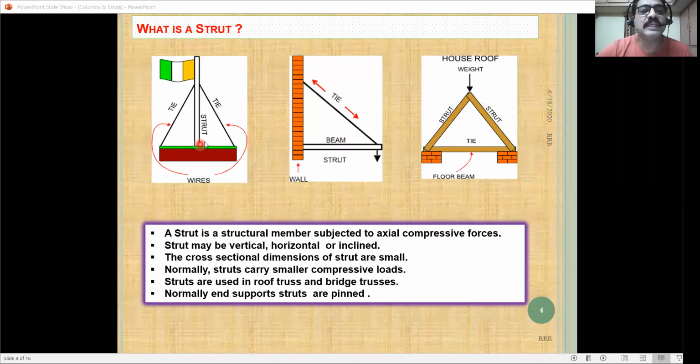The fixity may not be there. If your concrete is fixed, I mean to say a fixed condition is there, then we simply call it a column. But here it is not a fixed condition. It has the freedom to move in all directions, at least at the top or bottom. So that's why we call it a stud in this case.